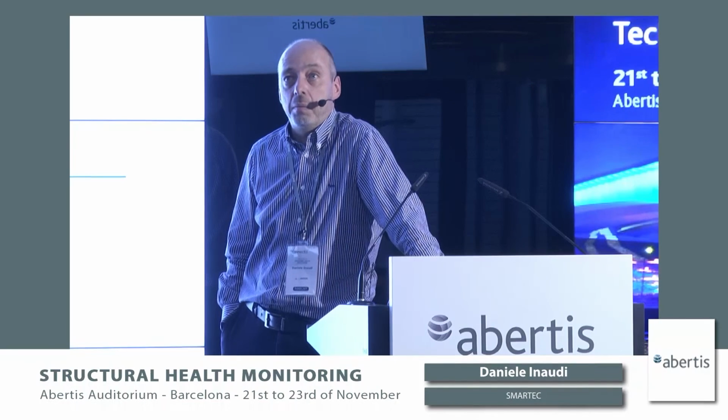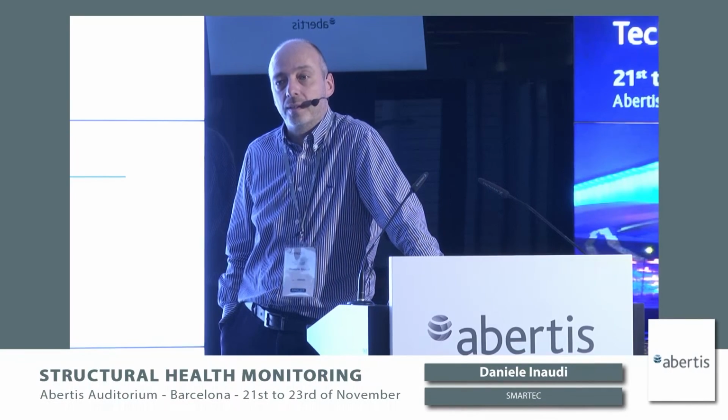So in that case, maybe you can count on 10 euros per meter or something like that to monitor a long extension. For example, the sinkhole project, the settlement example that I showed, was in this order of magnitude, 10 euros per meter. That's about what it costs to implement a distributed monitoring system.